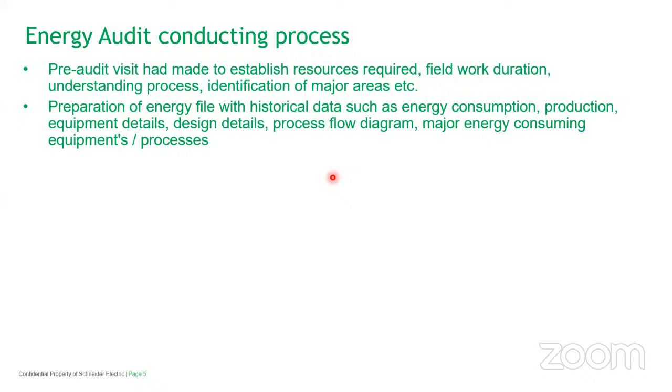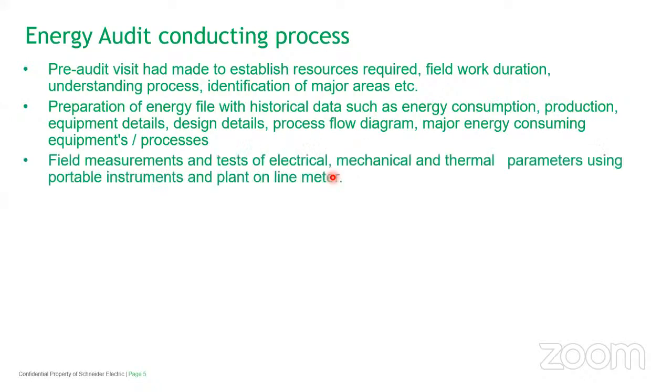And in buildings, some places they do the logbook recording. That means every hour or maybe every day they will go and record the energy consumption of the generator, the transformer, then your UPS loads, then your air conditioning system, lighting system. So somebody will log the energy data through an energy meter, whatever instruments are installed there, and it is captured. So this is the second preparation we do.